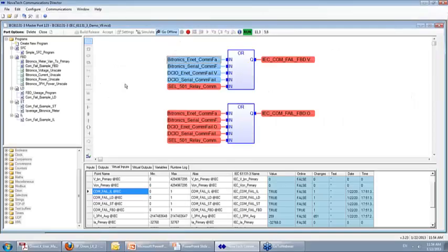Back to our programming environment online, you can see that the tree has blocks indicating the types of programs which we have created. To create a new program, we would go into Create New Program, and it would give us the luxury of selecting one of the various languages. If you have selected a language and wish to convert it to another language, the IEC logic does allow that within the NCD configuration and programming environment.